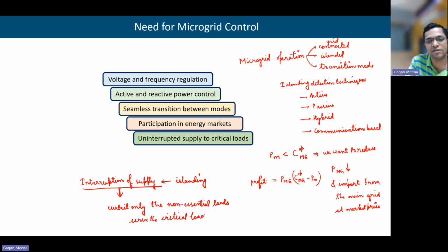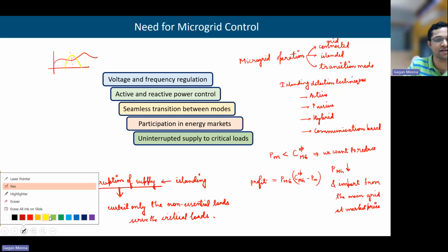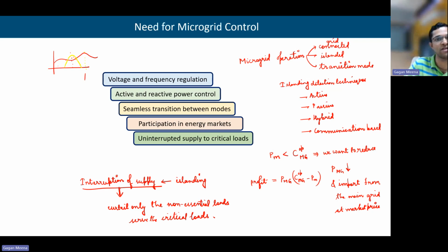Because there are constraints on the storage. In islanding operation, the storage would be working, right? Let's say in evening time when renewable is not there, only storage is there. So this is the peak time. Here, solar is during this daytime. Let me change the color of this. Okay, so this is the solar time. Now this is the peak time, and here solar energy is not available, but the battery has already charged using that during the daytime. Now the battery can discharge here.